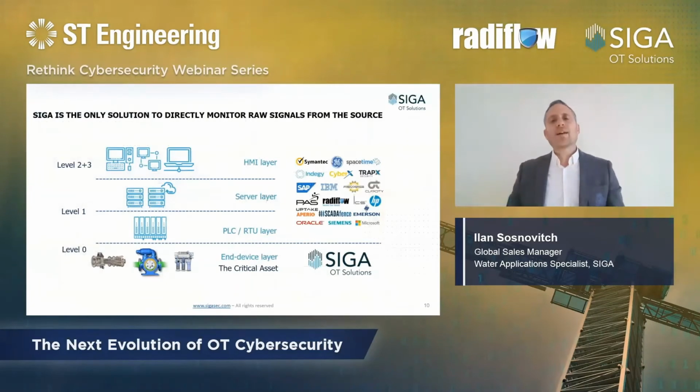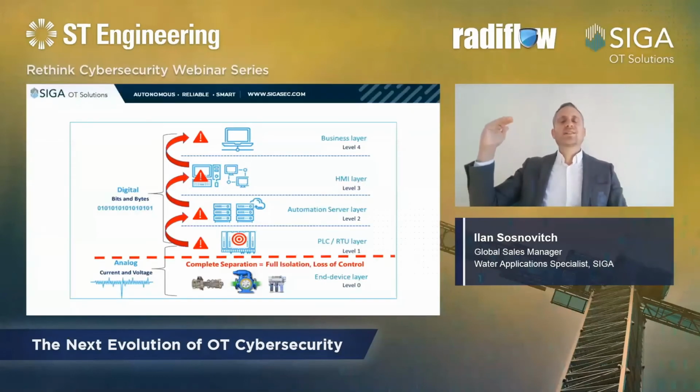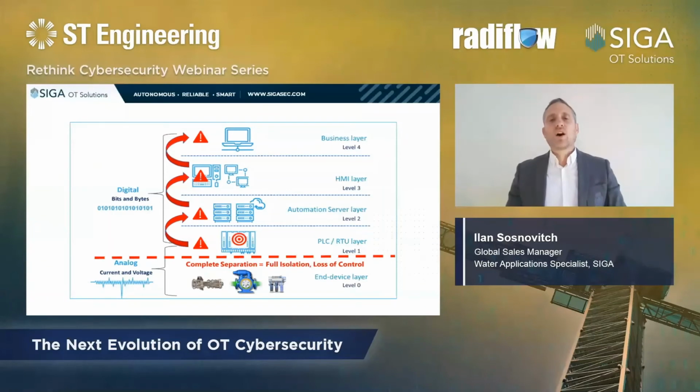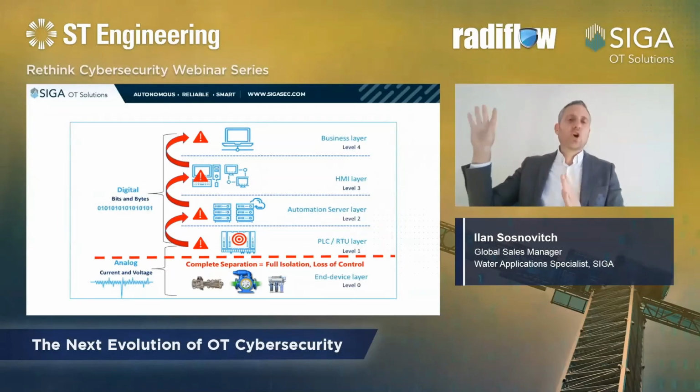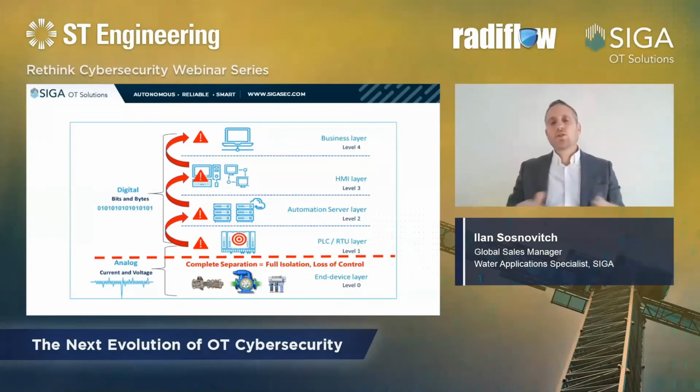Let's look at a very famous attack, a Stuxnet-like situation, where someone was able to infiltrate the PLC and change the logic of the PLC. He does this while giving a totally different representation in the upper layers, so that people on the HMI level or the operating station level think that everything is okay, because the hacker was able to manipulate the data in the HMI to show that everything is fine, while a totally different situation is happening in level 0.